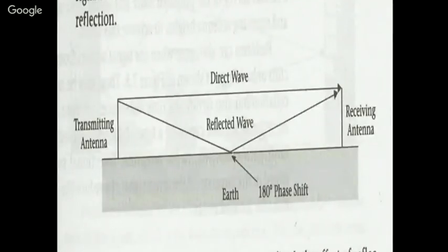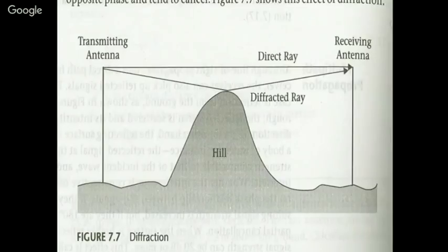Say this is one case of reflection. Signal strength will go on changing. If the signal is multi-reflected, maybe you get the same signal from two places. Maybe one is delayed, and one is the direct one. It will not be exactly at the same location.